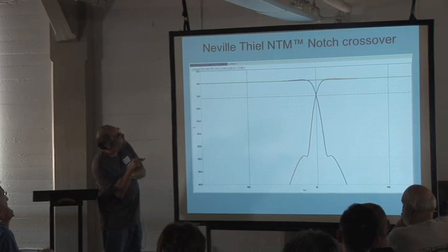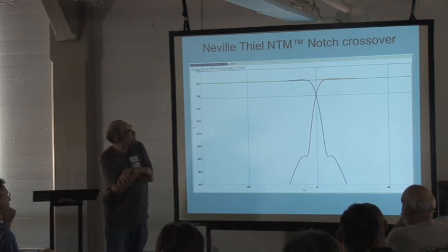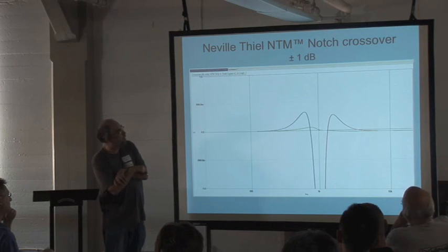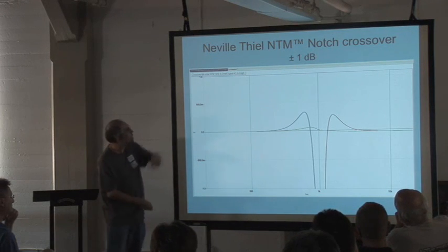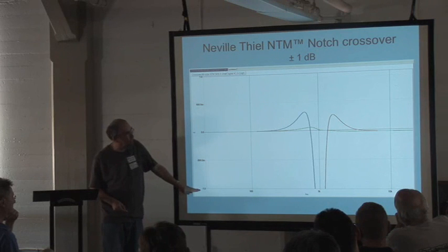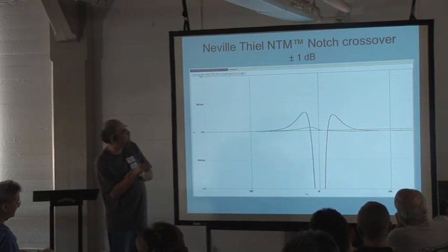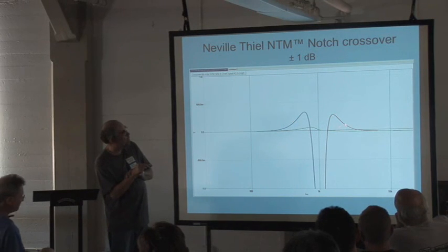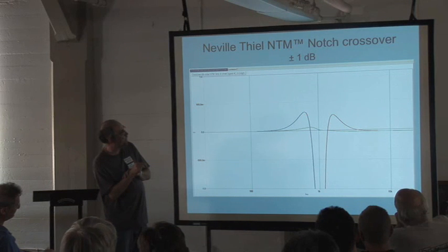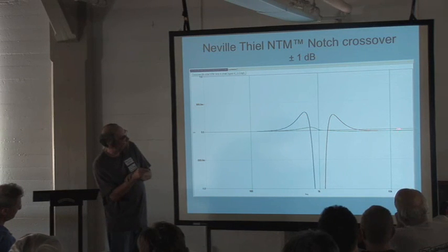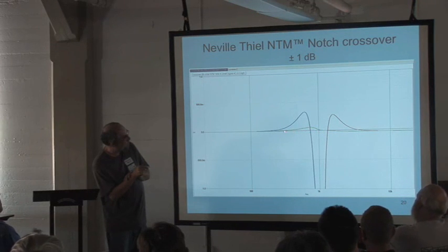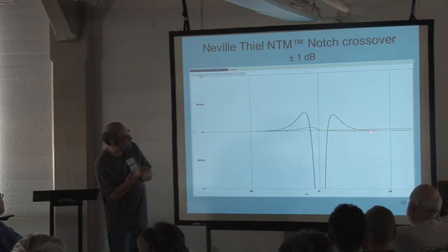Okay, now you can't see it very well here, but there's a line there which indicates it's something to flat. Next please. Right, so we zoom in mightily, so you've got 1 dB, minus 1 dB, and this is what you get. The 2 filters, the HF filter there and the LF filter there, have this response with this carefully controlled little peak there. And now if you sum those 2 together, you get this green line here, which I hope you can see. Now, I will be honest, I'm not sure I've got that quite right.